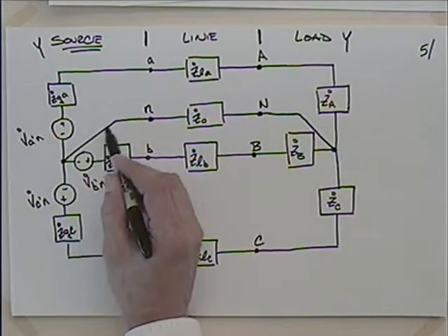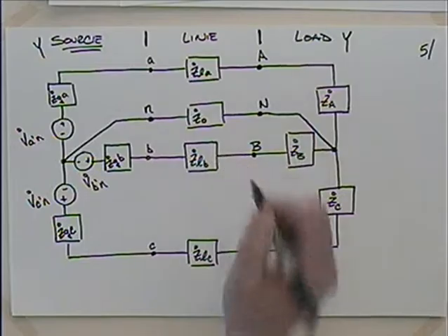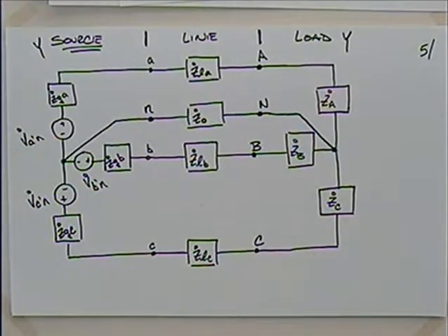We also have, because we've got a Y, this neutral, and I don't know what to call a neutral, so I'll just say it's Z naught. It's probably not going to be a big deal, as you'll see in a little bit. Yes? For line loss, do they have resistance like per foot per wire? Uh-huh. Yeah. It's usually pretty small. Depends also on how much current. Remember, it's kind of a vicious circle, because as you start to pull too much through it, it'll heat up, and as the temperature increases, the resistance will increase.